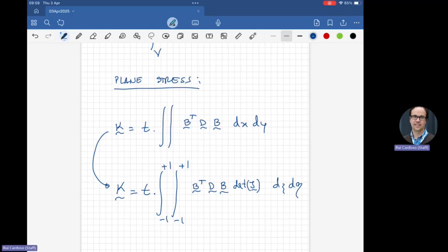And then you can do your mesh with many different shapes of elements, and it will always work for any element, because we do the mapping between this physical domain where your elements are distorted to this parametric domain where your element is always a perfect square. Okay? That is the advantage of this. So I cannot tell you that with the strut element. That's why I'm moving now to plane stress. Okay? Yes, sir.